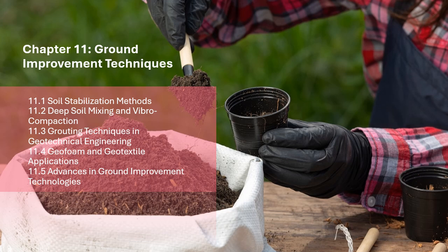1.1.2.2.3 Advantages of vibrocompaction. Increased density and strength. Vibrocompaction significantly increases the density of loose granular soils, thereby improving their strength and stability. Reduce settlement.